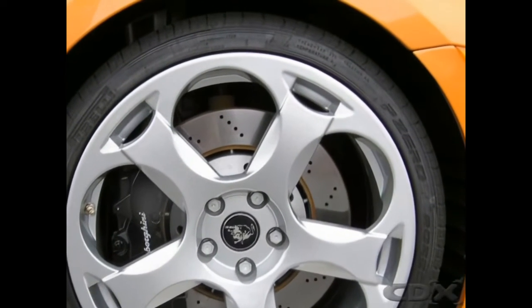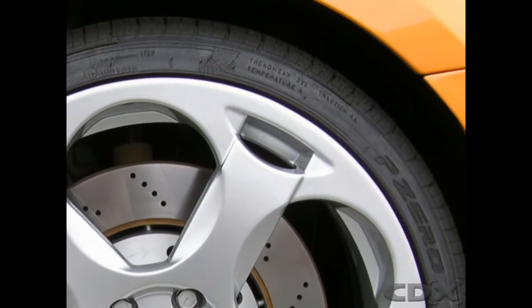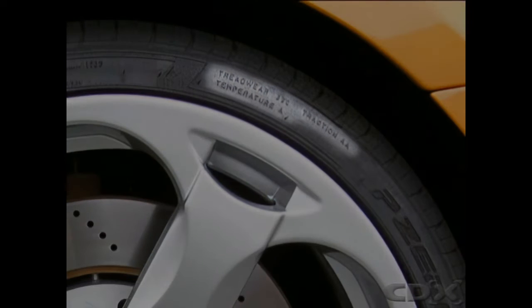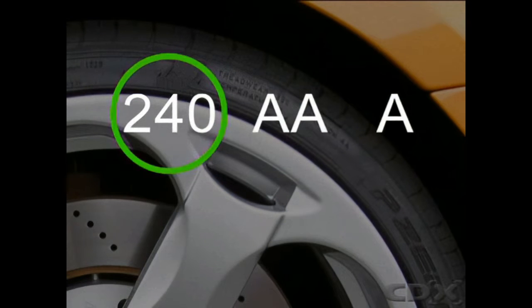One of the markings on the sidewall of a tire is a Uniform Tire Quality Grading, or UTQG grade. The tire's UTQG rating provides information on three aspects of the tire's durability and operational characteristics. They are tread wear, traction, and temperature. The tread wear number comes from testing the tire in controlled conditions. The higher the number, the longer the life expectancy of the tread.